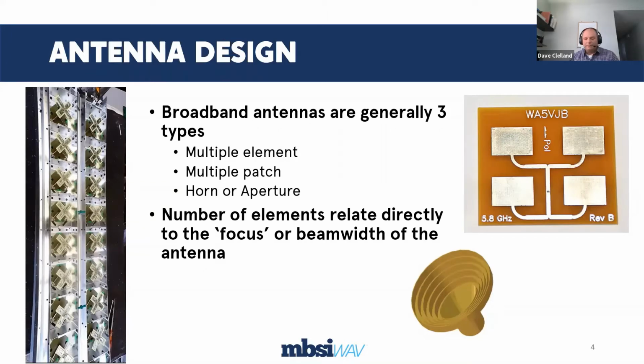Now, this is a graphic of what a couple of different types of antennas look like with the cover off. Many people have never had the cover off of a sectoral antenna on the left here. And so what we have here is a stack of elements. In this case, this is a left and right slant antenna. It's a 2-port, 65-degree antenna. You can see that there's multiple arrays. These elements that you see here are a form of a patch antenna, not unlike the patch antenna that's on the right-hand side of the slide here, but they're tuned so that they give very particular characteristics.